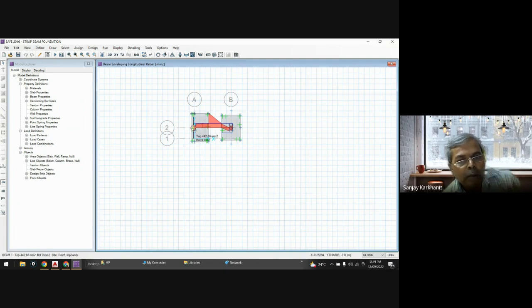You can see at bottom here, you need 0. As you go on this, you will see that at bottom, you do not need any reinforcement at all. You can check it. But here you need something 368. So let us provide 4 bars of 12 dia bar at bottom.